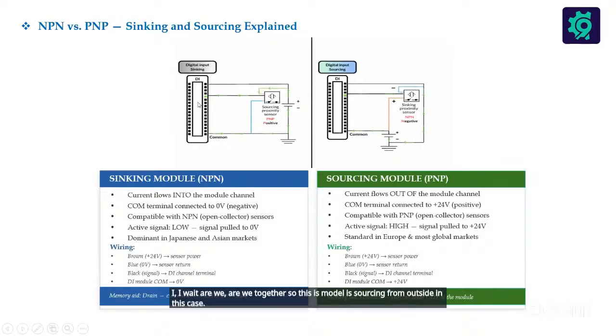Now, in this case, the positive is entering into the PLC through the sensor, and then the negative is coming out of the PLC, which is why this module is considered a sinking module.